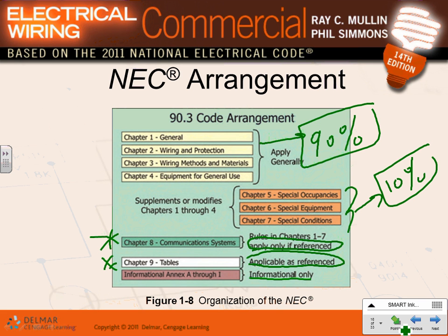And these are my numbers related. It tells you how many conductors you can fit in a conduit. If you go to a number 14 conductor in a rigid conduit, 3/4 of an inch, first you're going to go to Chapter 3, to the article that talks about rigid.